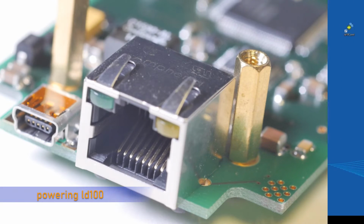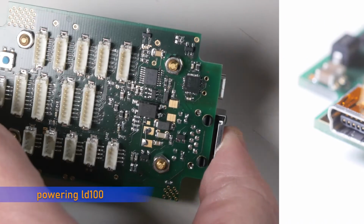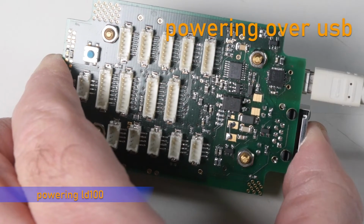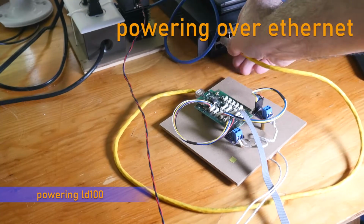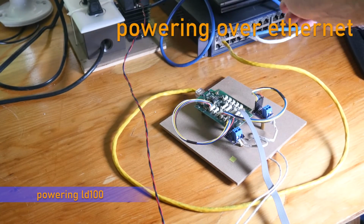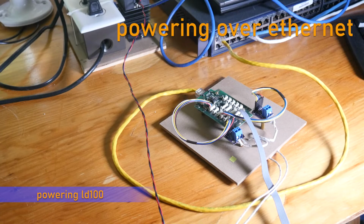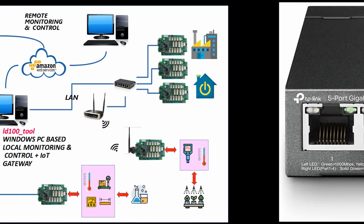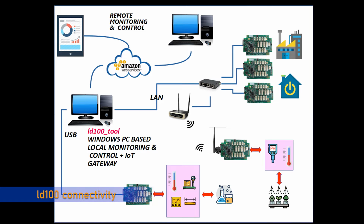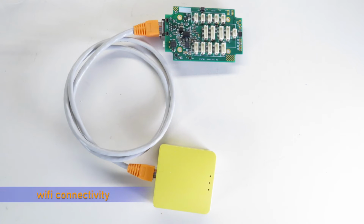You can power the LD100 board over either USB or power over Ethernet. To power over Ethernet, you need a special type of network switch that provides power over the Ethernet cable. These kinds of switches are widely used for IP cameras and IP telephones. You can connect to the LD100 board over either USB or Ethernet. Inexpensive Wi-Fi adapters can be connected over Ethernet for wireless networking.